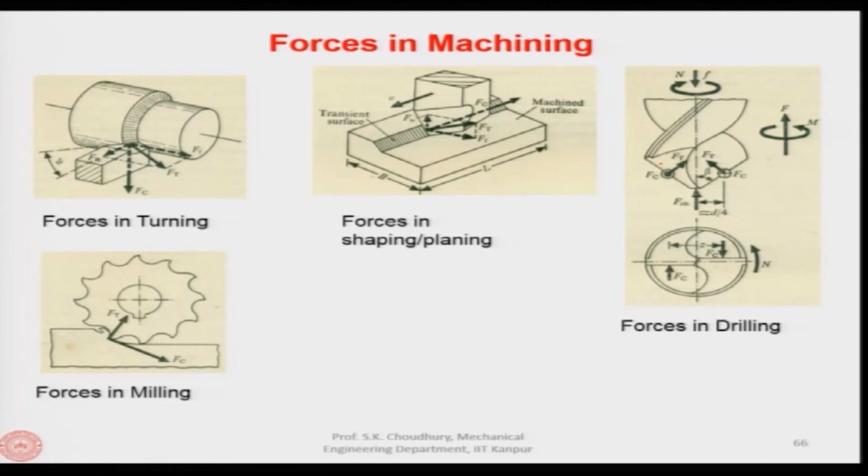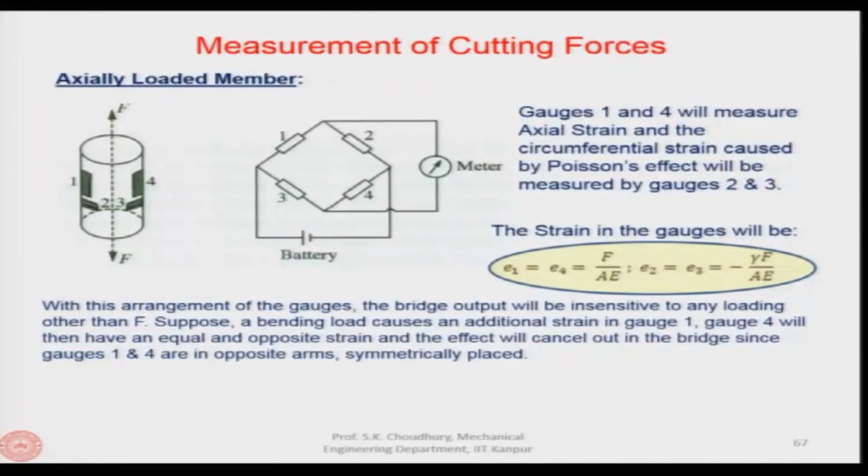Now, how to measure these forces? That becomes a problem, because if you can measure the forces in turning by an instrument, that instrument cannot be used for measuring the forces in shaping, for example, or for measuring the forces in drilling or milling, because the forces are different. Forces, locations and directions, they are different. So, let us discuss the measurement of cutting forces.